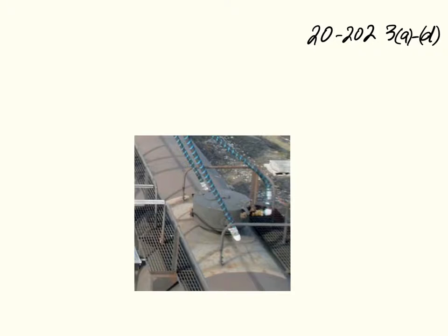So here what I've done is I've blown up an exploded view of where they're filling on this tanker car, and we're just going to look at the sphere that tells us about our zones. So once again, we have a Zone 1 location, essentially, that goes like this, and that extends in a radius either way 900 millimeters, and that we call a Zone 1 location.